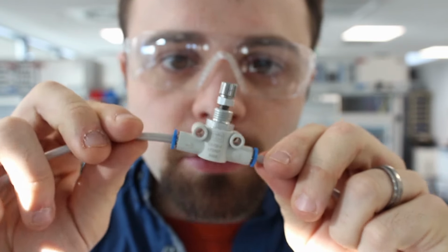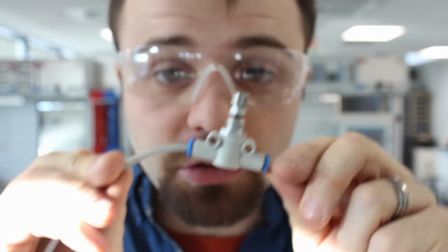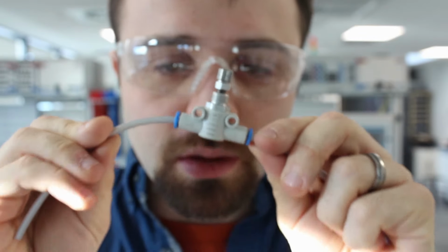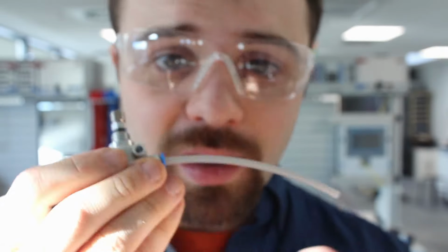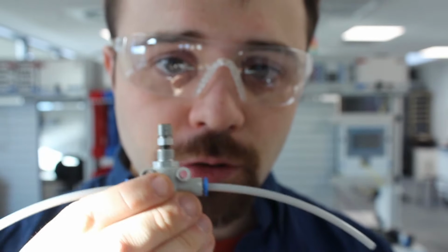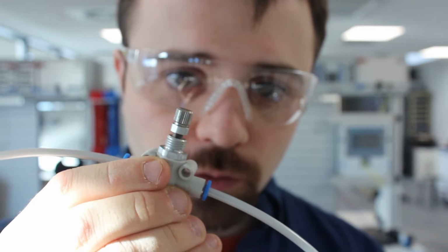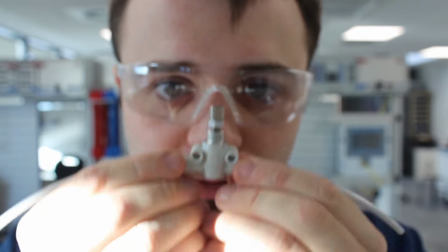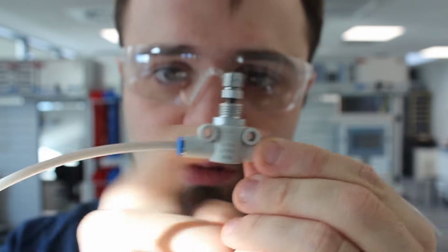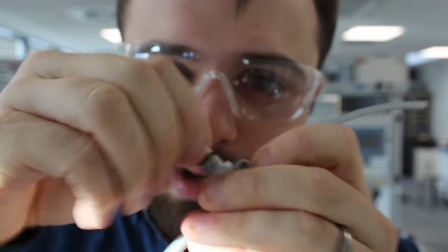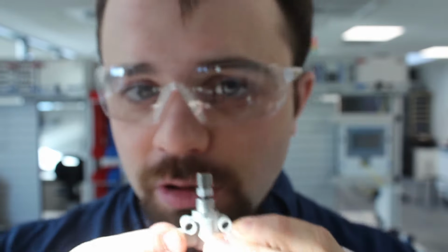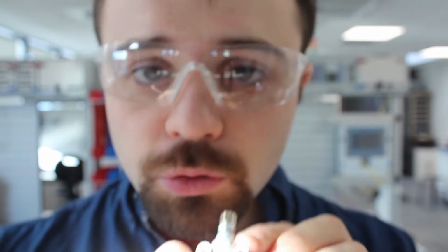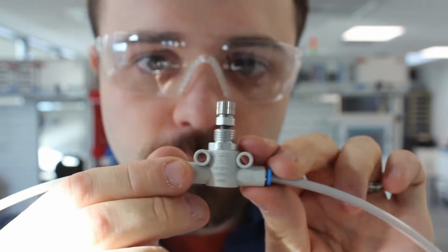Okay, close-up time again. In this next bit, we're going to be having a little look at this component, which is a flow restrictor. What these do is they limit the amount of flow of air into or out of a component, depending on which way round they're used. They look like just one component, which is a little plastic pipe through and then a lead screw, so you can screw or unscrew the amount of pressure to go through. But actually they're a little more complex than that. They also have a ball valve inside of them.